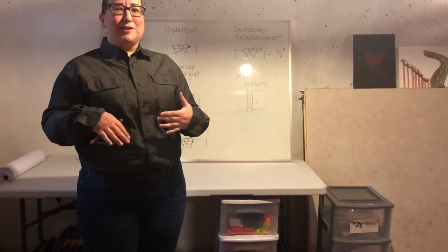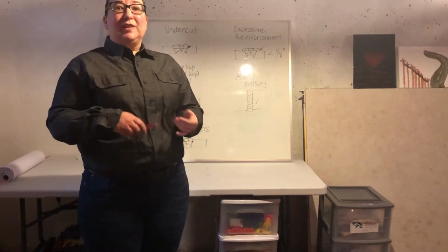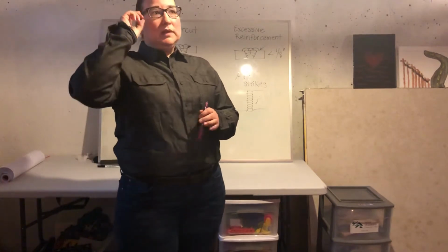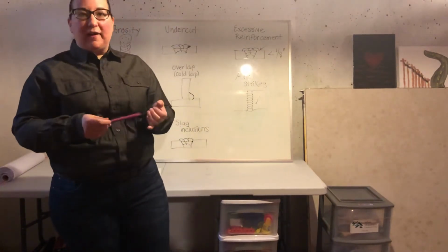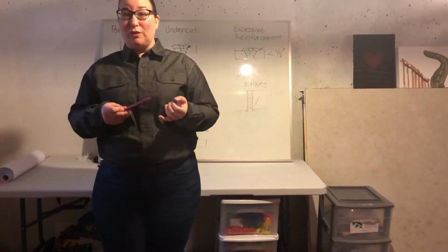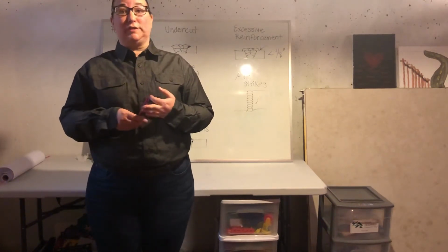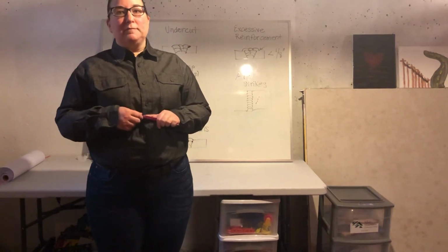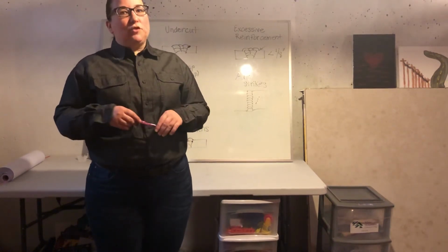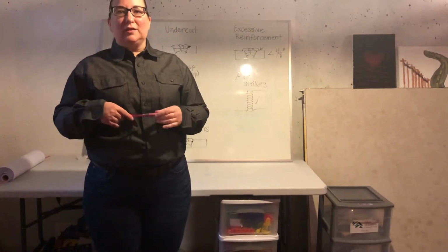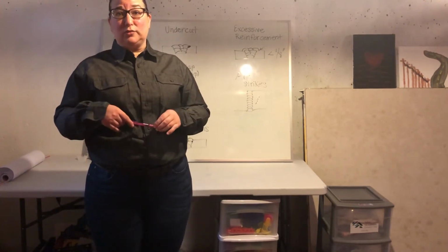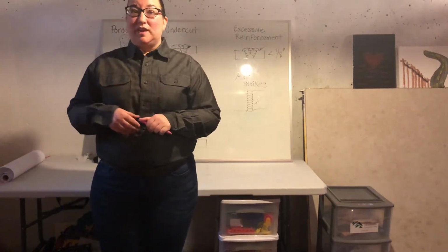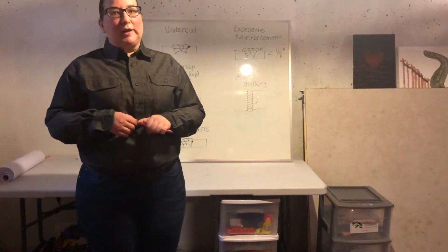Make sure you have everything you need in your booth to clean your weld and to run the weld in between. Some tools we want to have with us, files, and I'll get to why those are important in a second. So our files, our chipping hammers, and our brushes. Stainless steel brushes are really great for helping clean our weld and base metal. Grinders too, we don't like to grind, but if we have to, we can grind. Some procedures do allow us to do that, especially if we get one of these discontinuities. We have to make sure we take that out instead of just welding over it.